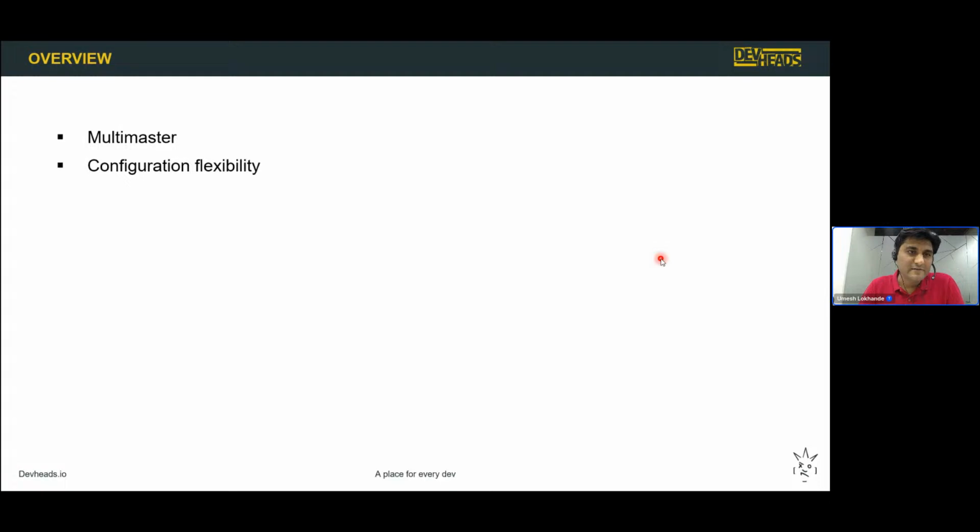Then in the CAN, we have configuration flexibility. We can configure the baud rate and other settings. We'll get into that in a moment. We can also make the messages prioritized. So let's say you have a certain message in your embedded system or solution which is really very important, just like in a vehicle, you have an airbag, which is very, very important, and it has to fire up. So it has to have the highest priority. So you can set the priorities so that whatever data is important, you can put at high priority.